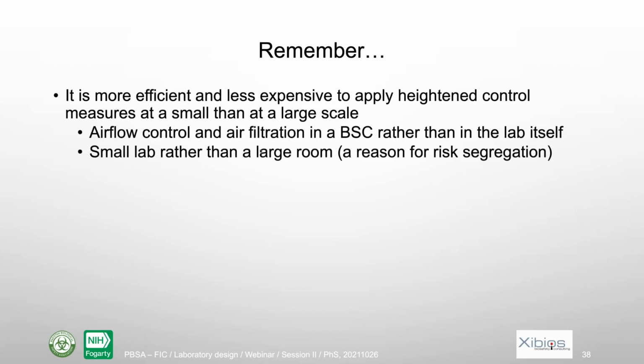Another principle that is very important to remind is that it's more efficient and less expensive to apply high control measures at a small scale than at a large scale. So if you can have a biosafety cabinet, and using a biosafety cabinet will prevent you from having sophisticated secondary containment measures, it will be better, because the biosafety cabinet will work on a small volume of air and will have good filters and so on.